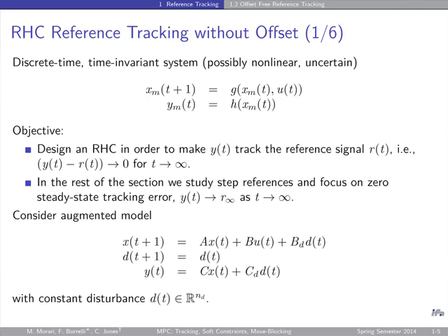Okay. I can use it to define in this lower equation my targets for the MPC controller, and this XT and the UT goes in here. Otherwise, I have basically exactly the same equations I had before: my system model, my constraints, my disturbance equation. The initial condition for the prediction starts with the estimated state. The initial condition for the disturbance starts with the estimated disturbance, etc.